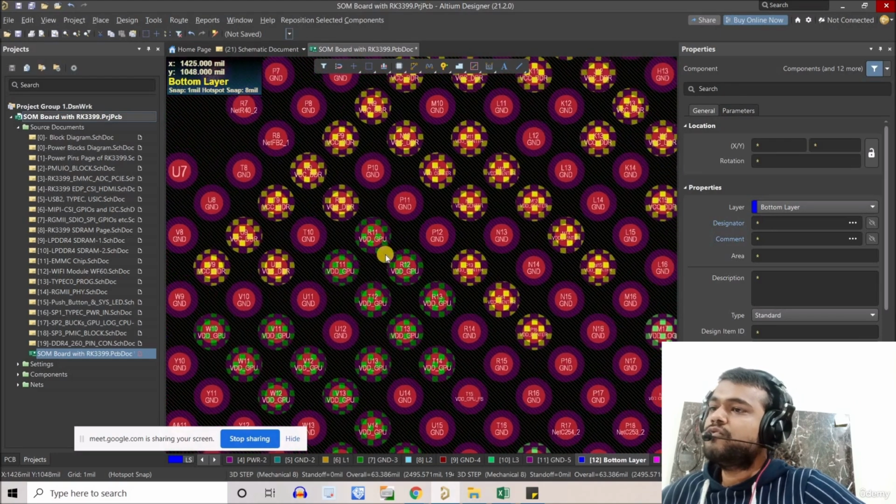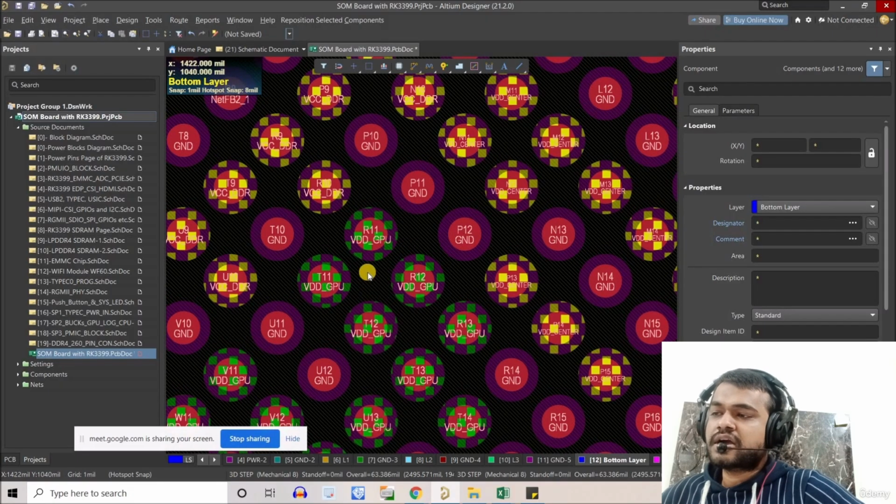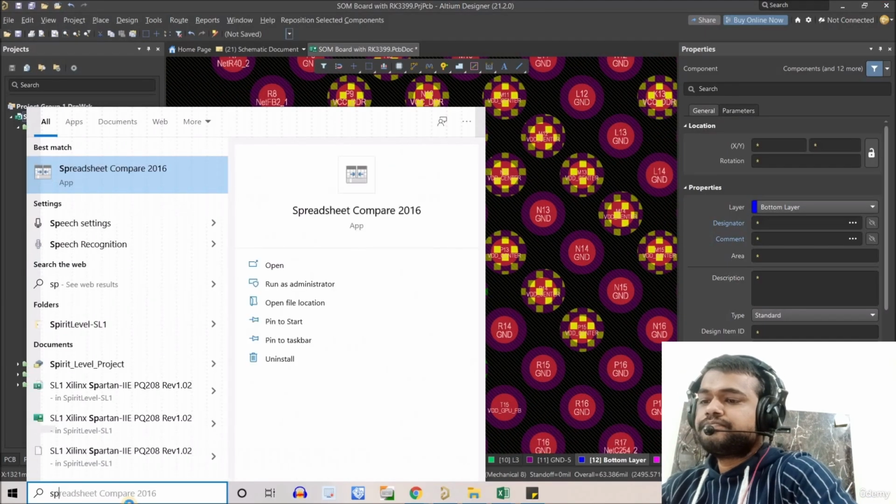For example, we have these 4 vias. For these 4 vias, what should be the orientation of the capacitors? So here, the capacitor's power pad will be on this side and the ground pad will be on this side. Okay, let me snip this one so I can draw.